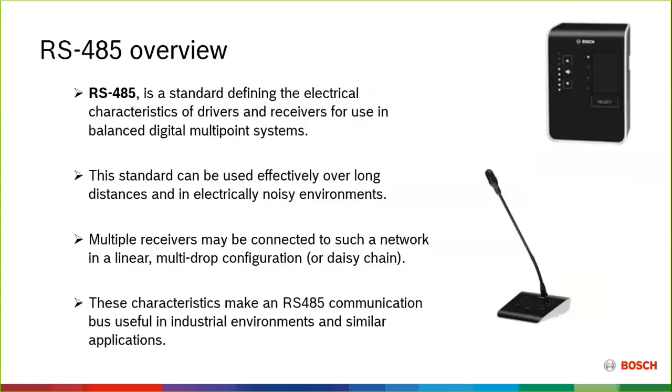As far as what we're using, RS485 is the protocol we're using for control. And I'm sure most people have heard of it. It's been around a very long time. Our only note here is about third-party products. We get asked a lot, can other third-party RS485 products be in this daisy chain? And we would say no. This daisy chain is for call stations and wall control panels specific to the PLENA Matrix product family.